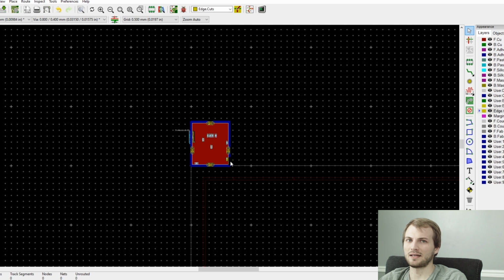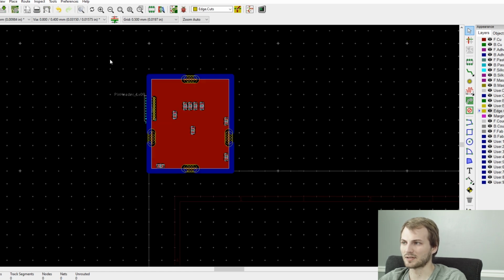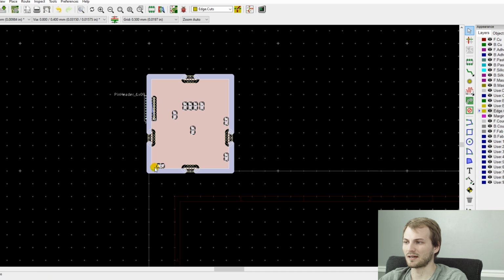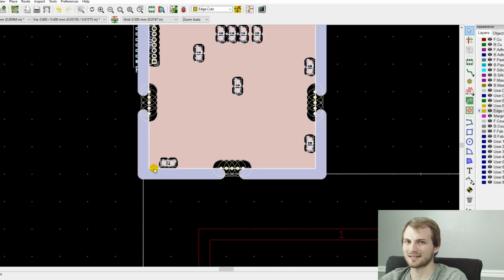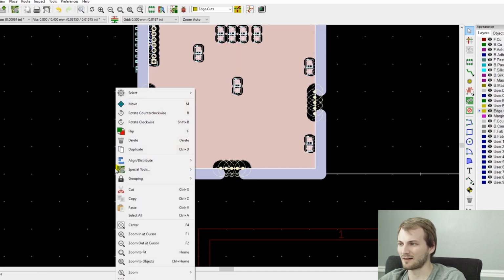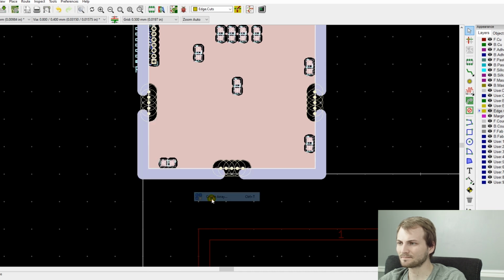So I would rather give up a little bit of real estate and pay a little more per panel than have the boards warp. That's, again, personal preference. Most people want to squeeze every board out of the panel size to save some money, but I think that comes back to bite you in the long run.